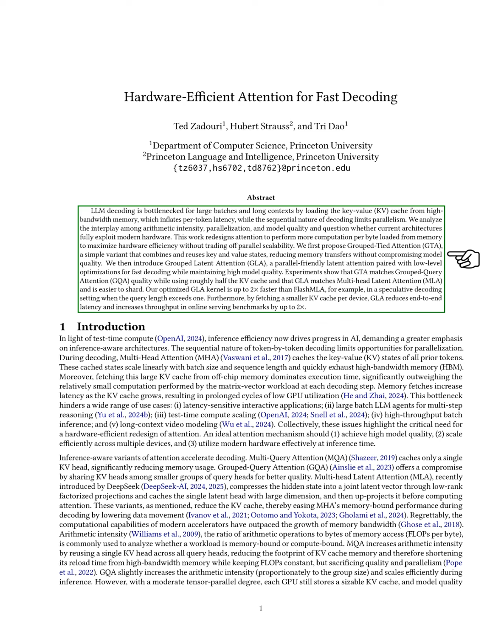In terms of performance, we classify operations as compute-bound or memory-bound based on their arithmetic intensity, which is the ratio of arithmetic operations to memory accessed. An operation is compute-bound if it is primarily limited by arithmetic operations, while it is memory-bound if memory access time dominates. Our methodology focuses on designing hardware-efficient attention variants by maximizing arithmetic intensity and efficiently parallelizing across devices by linking key and value states and sharding the cached latent representation.